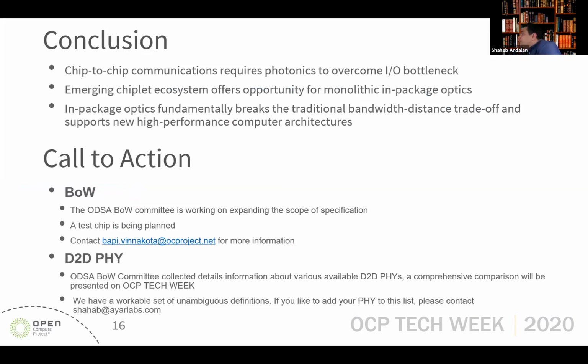Just as a conclusion, chip-to-chip communications requires photonics to overcome I/O bottlenecks. This is something that we believe and we should go for it. The emerging chiplet ecosystem offers opportunity for monolithic in-package optics, and in-package optics fundamentally breaks the traditional bandwidth-distance trade-offs that we have, and we are supporting new high-performance computer architectures.